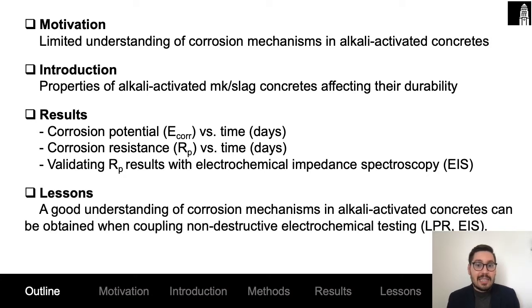One of the biggest lessons that we have learned from this project is that a good understanding of corrosion mechanisms in alkali-activated concretes can be really heightened by coupling non-destructive electrochemical techniques. The two main ones that we're going to focus on today are LPR and EIS. We'll finish this presentation with some conclusions, as usual.